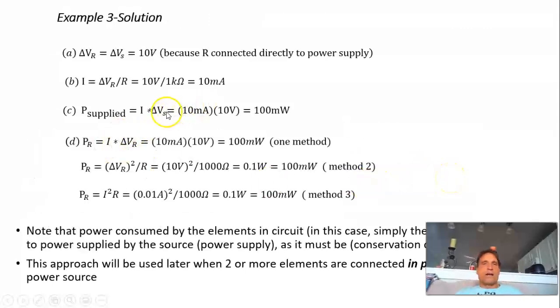And if we plug that in, 100 milliamps instead of 10, you would get 1 watt instead of 100 milliwatts. So in other words, the current and the power supplied by a battery depend on what's connected to it. The voltage is a property of the battery, and that's important, because the current depends on the battery's capability, but also on the circuit, on what's connected to it.